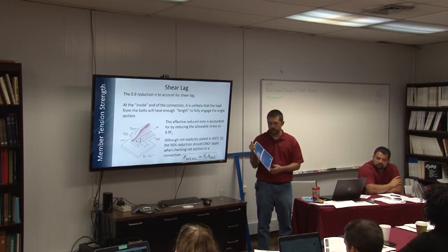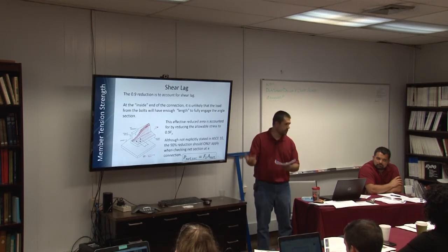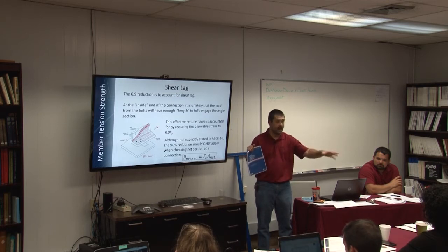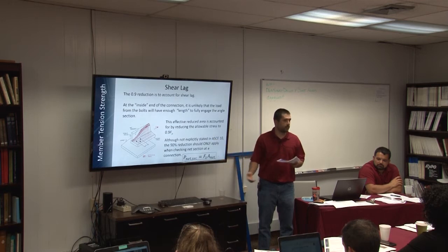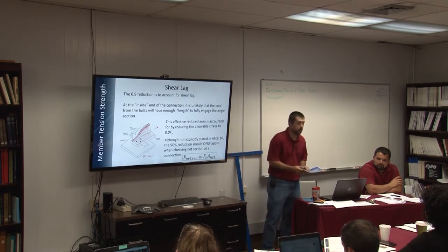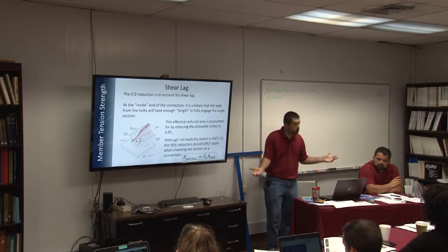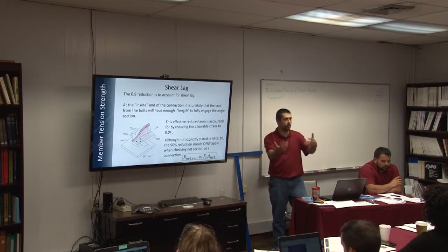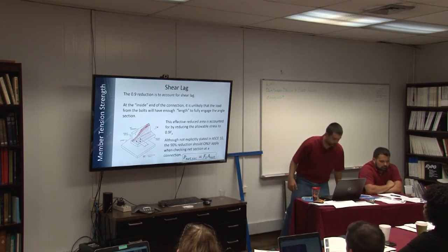And to formalize something into a standard, you have to make sure that you have equal representation from all parties involved: vendors, material people, engineers, those kinds of things. But eventually, I'd say 90% of what was in that manual of practice has come into this standard. Where I'm going with this is, a lot of the assumptions for limit state checks have just been around for a long time, and there are simplifications that have been proven with successful use. So what you're going to find a lot of times is the equations here may not be as thorough or as extensive as you see in the steel manual, but it's worked for the tower industry very well.